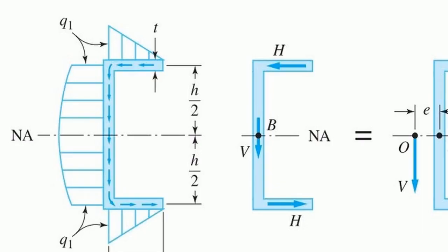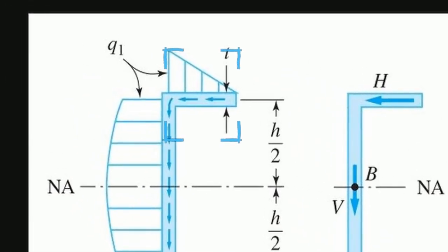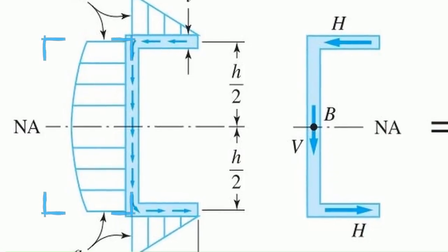As the force enters the top horizontal flange, it follows a specific geometric path. The triangular graph on the top flange shows the buildup. At the open outer edge, the shear flow is zero. It builds in a perfect linear slope as the energy moves inward. The flow then turns the 90-degree corner and enters the vertical web, accelerating as it carries the accumulated force.